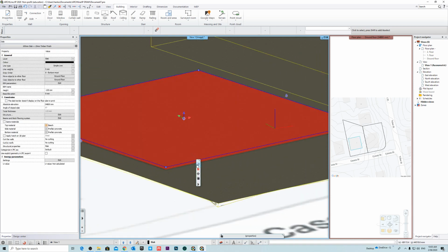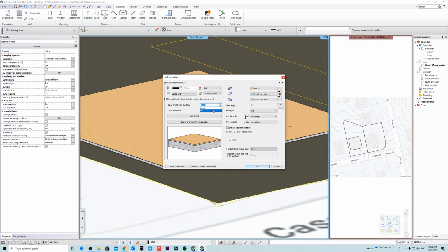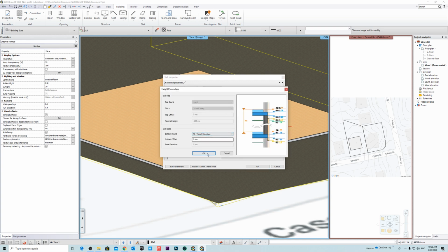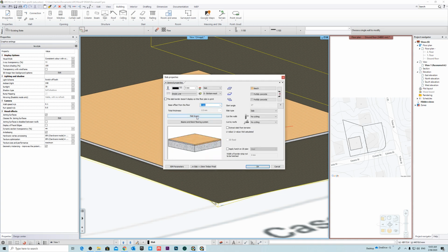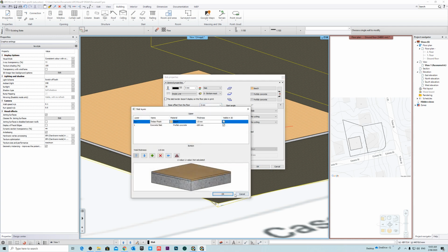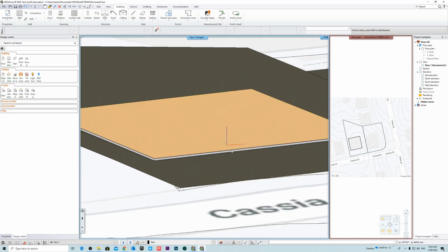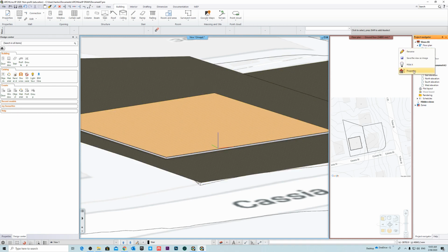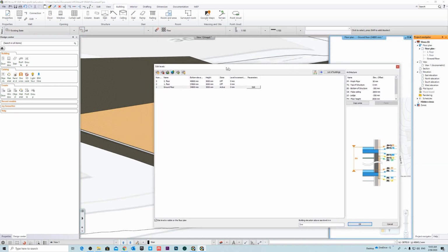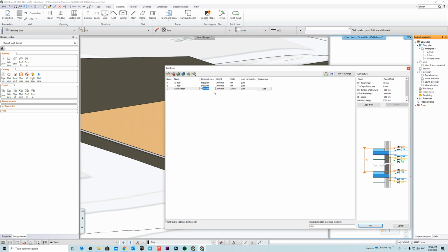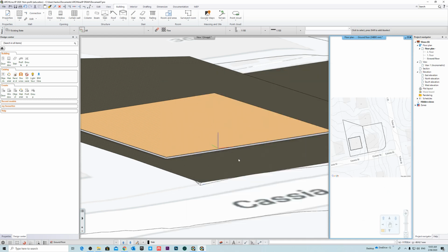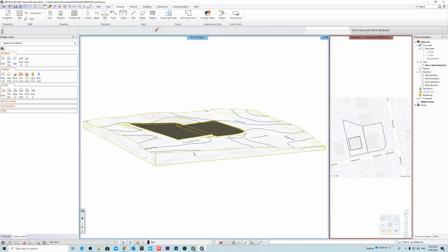All right, can go onto it, and we're going to select base offset from floor, top of structure, and that should be set. Slab layers, okay. All right, so that looks good. So we're just going to make a few adjustments. So we're going to go here to ground floor, and we're going to change how that slab sits there. So we're going to bring this down, let's say 34,500. Okay, and we're just going to hit rebuild.